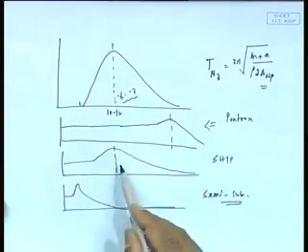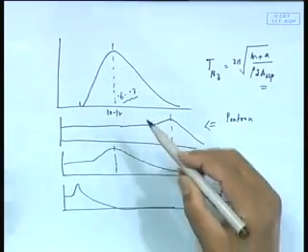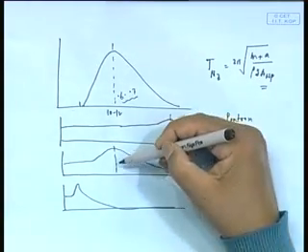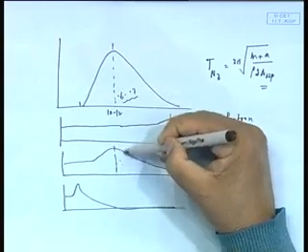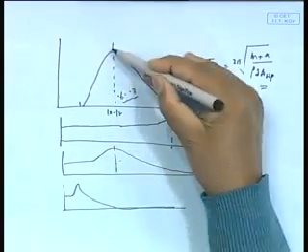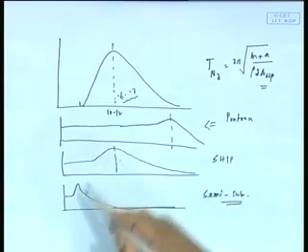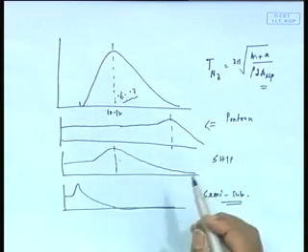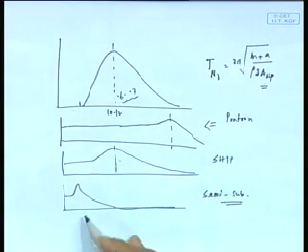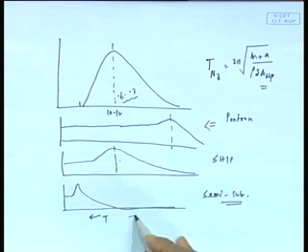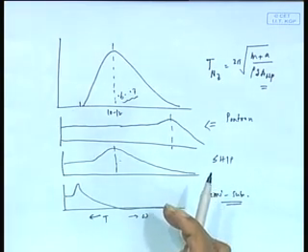Okay. Now, what we find is that we have tuning, I call it tuning. A ship would respond badly if its RAO, this part, gets tuned with the wave. You're saying semi-submersible has lower AWP. Much lower AWP. Then time period will be higher. Absolutely, this is omega, that is the period, no, this is omega. That is what I am saying, time period is 20 seconds or above.